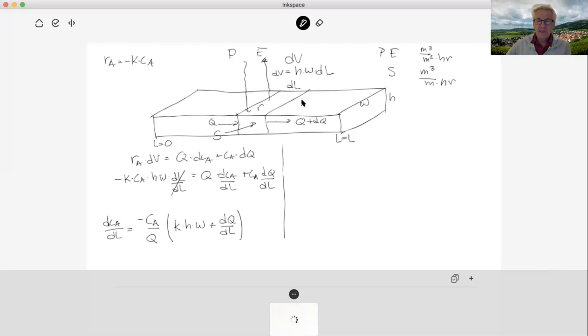So if we set up a mass balance for water, we have for this dV, we have the input of water, and then the next term is S, and that should be multiplied with dl, since it is per unit distance that the seepage is defined. And then we have the input from the precipitation, the rainfall, and that should be multiplied with the surface, right?